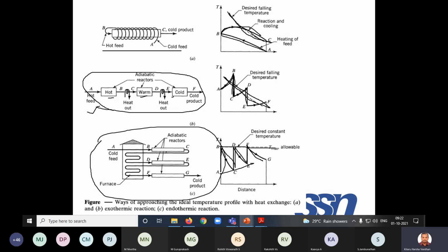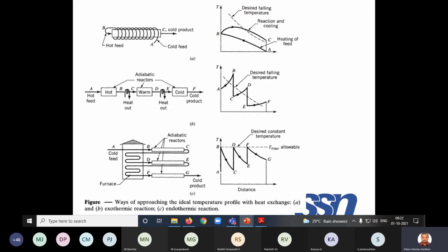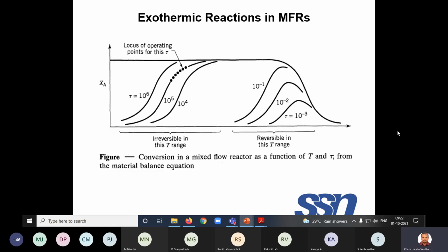So this is how you have to make the design, especially in adiabatic and non-adiabatic conditions, for exothermic and endothermic. So now you might have understood why there will be intercooling in between for exothermic reactions too, because you need to be on this particular line. For that line to be there, you want a high temperature, then come down, then go again, right? This I don't think is required for you, because it's very difficult to understand. If time permits, I will discuss this a bit later, right?